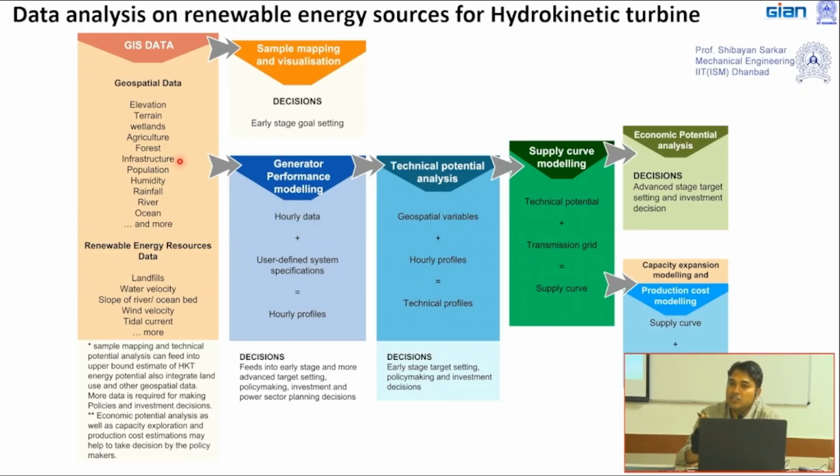To analyze both, different time series data is required. Either time series data corresponding to precipitation, which will be available from IMD, or the data measured by the Central Water Commission, available for a particular river and catchment. If either of these two data is missing, you have to go through a GIS exercise, where you will have some kind of estimation, and you have to do some survey in order to get your expected location and the cross section of this particular area.